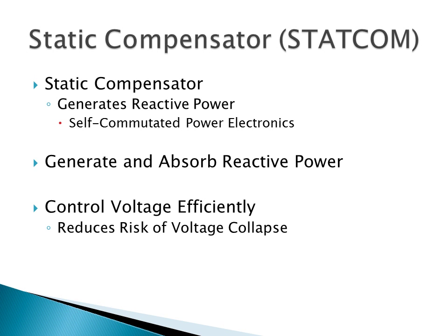The static compensator, or STATCOM for short, is a solid-state shunt-type device that generates reactive power using self-commutated power electronics instead of capacitors, inductors, and thyristors. It can generate and absorb reactive power about equally and control voltage efficiently. This in turn reduces the risk of voltage collapse.